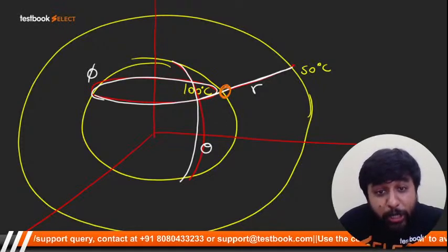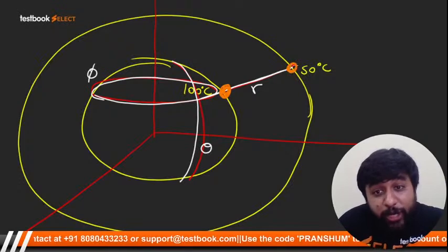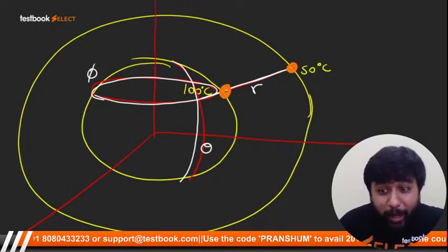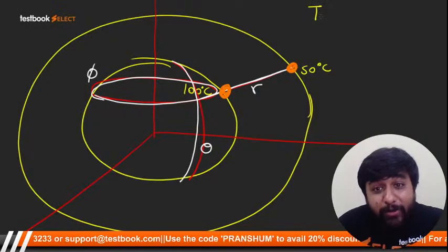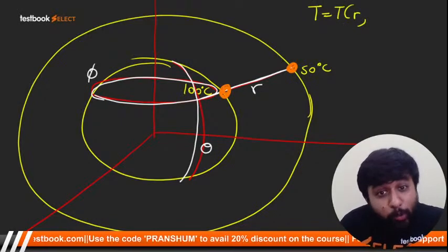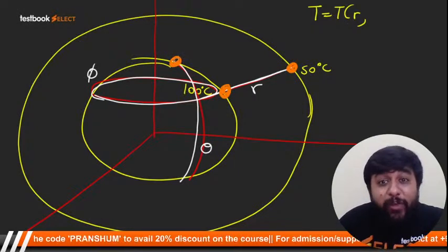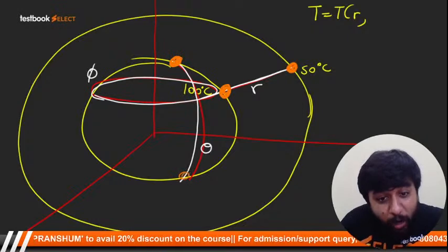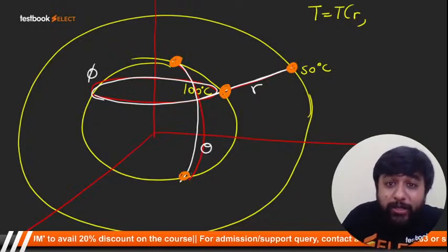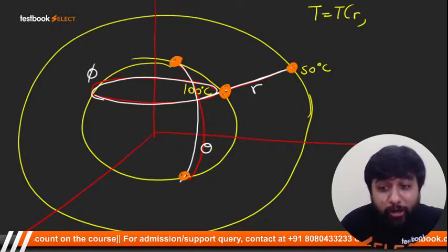So this point inner surface, temperature is 100, this point 50 degrees Celsius. So temperature is changing along R, temperature is a function of R. Now you take 2 points along theta. So what is this temperature? Inner surface 100 degrees Celsius. What is this temperature? 100 degrees Celsius. So temperature is not changing along theta.